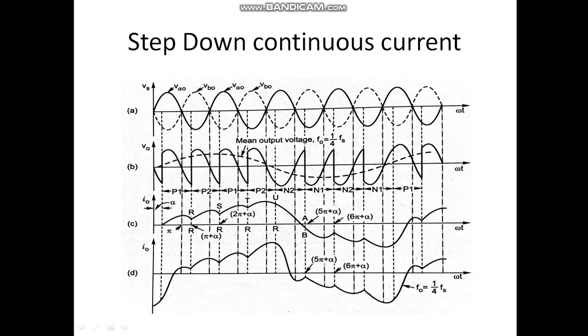So as P2 is turned on, this is now the starting point for current, so the current will increase from here again. Here our voltage polarity reverses, so it will come somewhat down. It is highly inductive, so it will not reach 0 suddenly, but at this point the next cycle starts. If the next cycle were negative, it would have come to 0, but the next cycle is positive, so now the starting point is this, so from here it will increase, it will go till here. Now at this point we have the reverse trend. So from here when we reverse it, it will reach 0, and on the reverse side it will start.